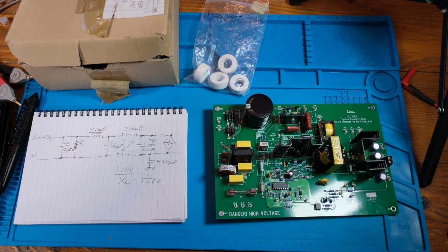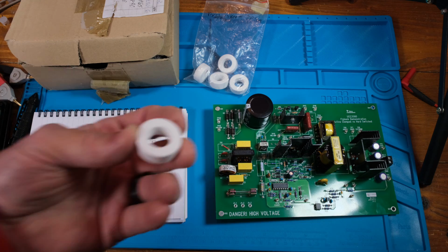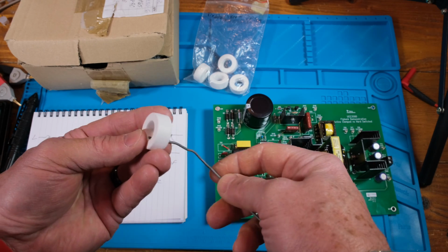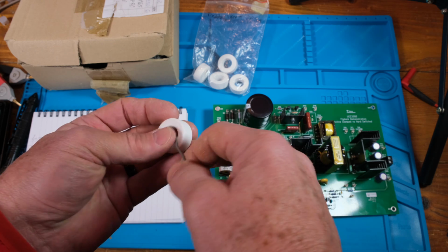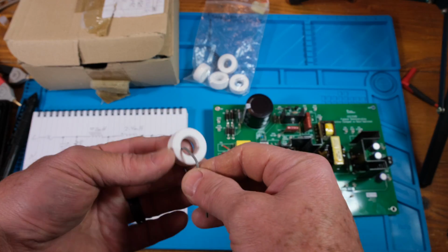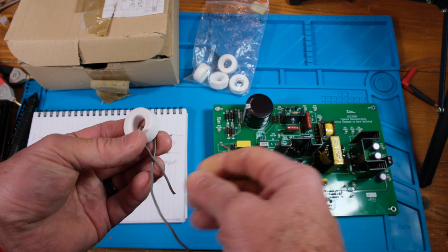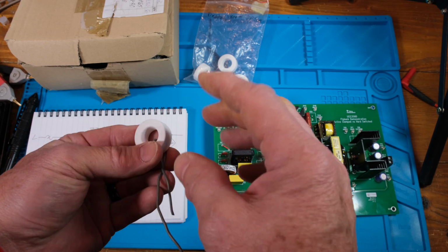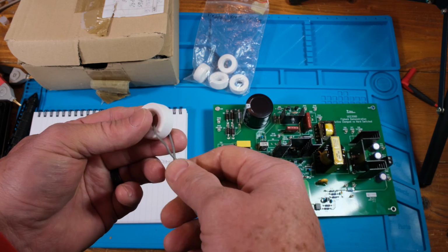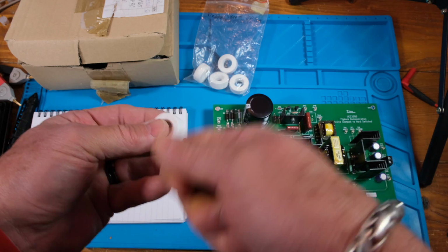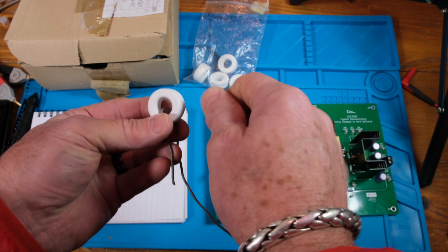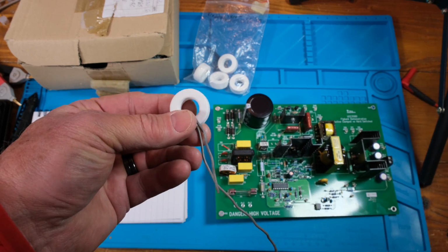But first, what I want to do is show you how we're going to do this. Here's our core. And here's our wire. It's insulated, and you can use any wire. If you're doing something for a certain design, obviously you need a wire that will carry the current. Now, if it's too stiff to wrap, you can use two smaller gauges that are equivalent and they're easier to wrap. It's called two in hand. You hold two of those small gauge wires, or even three wires with equal gauge, and you can use that. Okay.